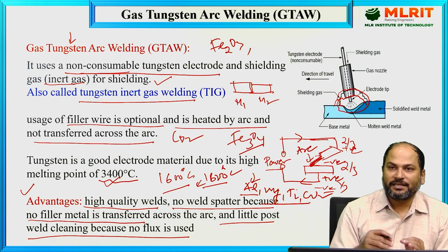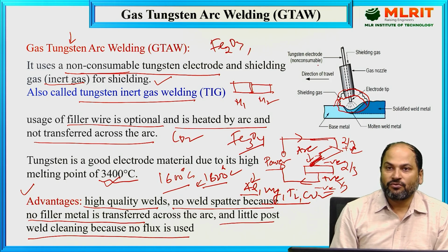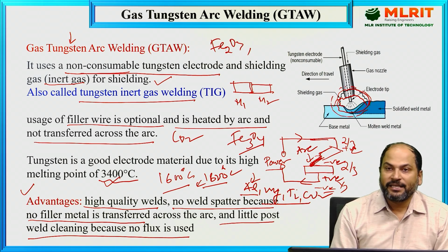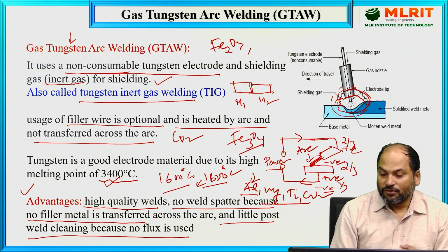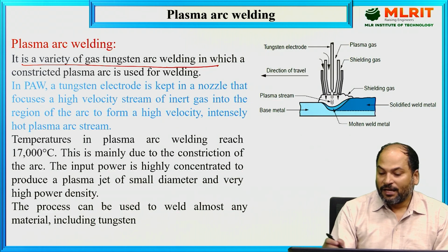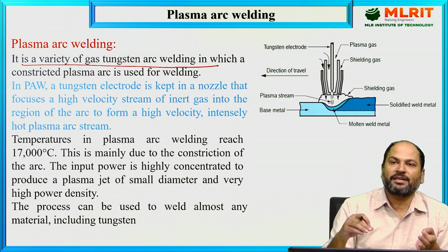We have created the arc, then we have provision for inert gases to flow in the area wherever we are doing the welding. Suppose this is the area where we are doing the welding. So gases are flowing, everything is the same. After that, what we do is force gases, generally inert gases, through a nozzle to pass through that arc at a very high speed.